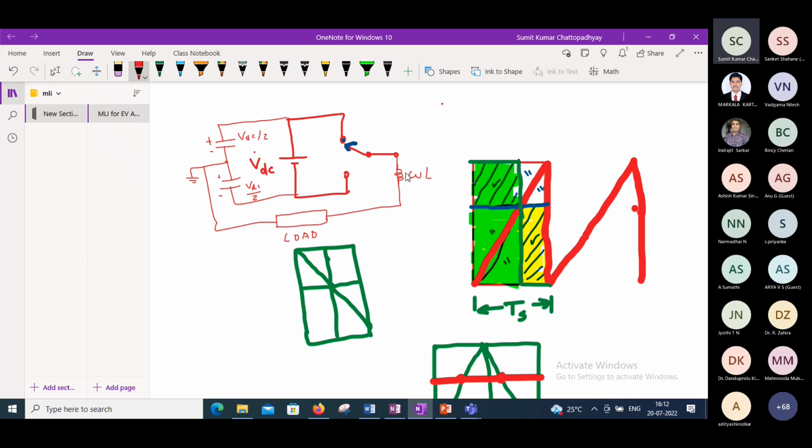Of course, the j term, I'm just talking about the magnitude of the impedance, not the phase shift. So if we analyze the PWM output voltage, it has lots of harmonic components, but those are higher order harmonics where omega is very high, so they see very high impedance and get filtered out. That has negligible effect. However, it has several disadvantages, like this switch is continuously switching between plus VDC and 0,